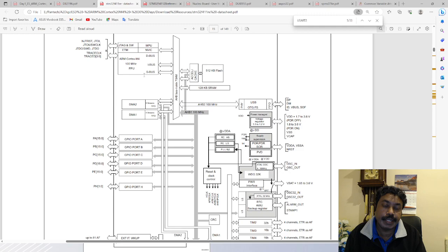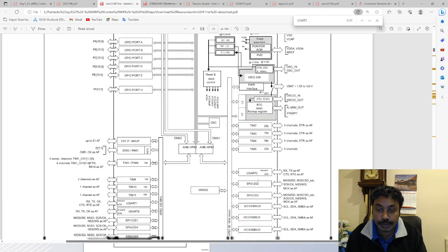So we learned yesterday, or the other session, this is a microcontroller and it's communicating via the AHB bus matrix, and it's connected to AHB1. The AHB1 communicates via the GPIO port A. So we're going to use GPIO port A, and in this study we are using USART2. That means we're going to use transmit and receive. So both have to be set as PA2 for transmit and PA3 for receive.